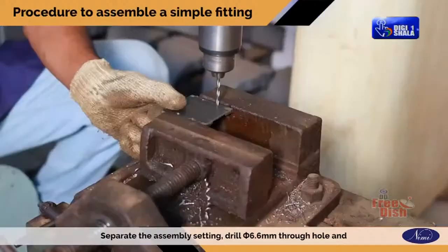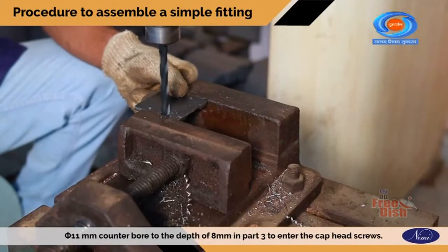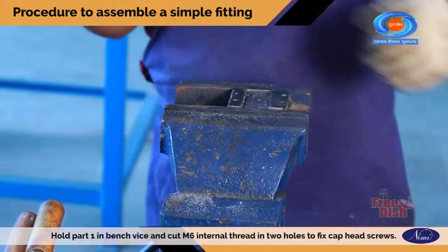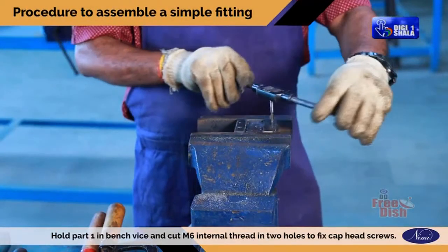Separate the assembly setting. Drill a 6.6 mm diameter through hole and an 11 mm diameter counterbore to a depth of 8 mm in part 3 to accommodate the cap head screws. Hold part 1 in the bench vise and cut an M6 internal thread in 2 holes to fix the cap head screws.